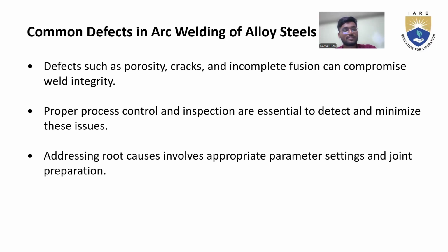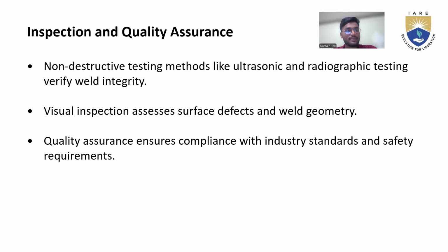Another one is addressing root causes, which involves appropriate parameter settings and joint preparation. And inspection and quality assurance. Non-destructive testing methods like ultrasonic and radiographic testing verify weld integrity, and visual inspection assesses surface defects and weld geometry.